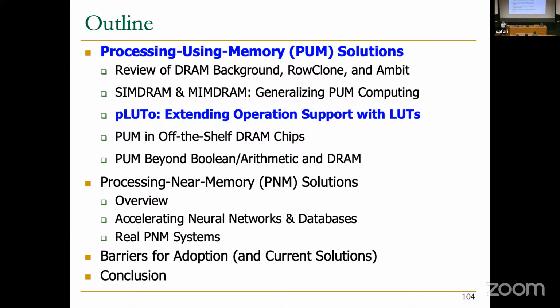This is basically a refresh operation, which is what RowHammer mitigation solutions usually use to mitigate attacks, right? So if you don't consider the blast effect, and only consider the compute rows where you are doing the computation, because these are the rows that you keep activating all the time, this is not necessarily more susceptible to RowHammer than regular DRAM, because again, you're just refreshing those rows constantly every time that you do a triple row activation.